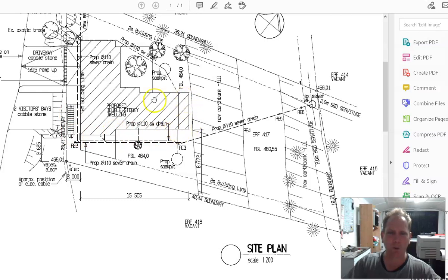On a site plan, all you need is the building hatched. Because what you've got in a site plan are contours and things like building lines. So there's your boundary. Boundaries should have dimensions on. There's your building line. Building lines must be named. And the width, that's a 2 meter building line because that's 2 meters wide.